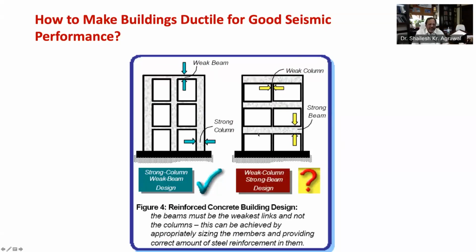The seismic inertia force is generated at its floor levels. Remember, I explained to you in the earlier tip that due to ground shaking, inertia forces are developed at different floor levels in the building. So these inertia forces are transferred through various beams and columns to the ground. So the correct building components need to be made ductile.